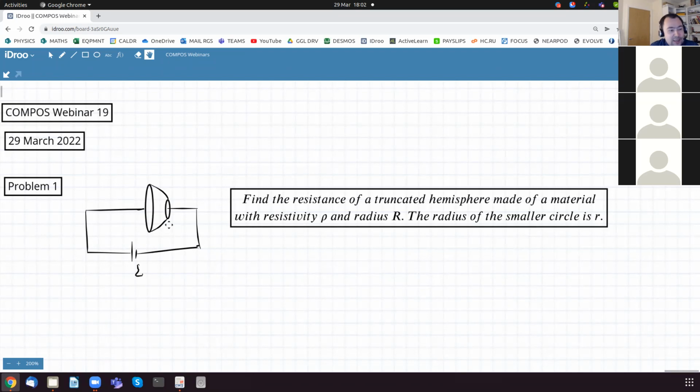If we don't cut off the slab on the edge, we're going to get some really weird results, as in the cross-sectional area becomes 0, so the resistance becomes infinitely large. So it's a whole mess down there. So I left it simple. So we have the left edge has radius r, and this edge has radius r small.